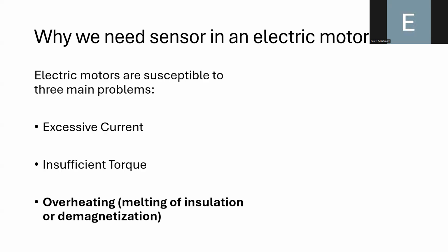One goal is oriented to the fact that we want to control, for example, the speed or the torque that the machine is providing to the system that we want to move. In that regard, we need to use speed sensors, in particular what is called an encoder, or maybe we need to measure the torque that the motor is delivering to the load. And in order to do that, we need to use a load cell, in order to measure how much torque the motor is providing to the system that we want to move.